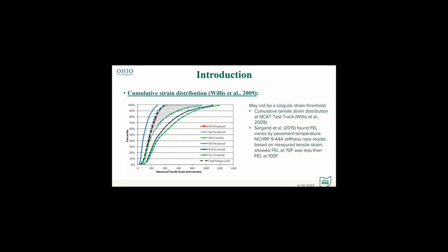That included the work that was done in the APLF with the highly polymer modified material, and also one more recent section, part of the 2015 report. I think it was constructed in 2012. So that's what we did. We developed a cumulative strain distribution that was calibrated to Ohio test sections using material properties that we had. What you're looking at on the screen was developed using back calculated modulus. We used dynamic modulus because we had more consistent data that way. Does that address question 1?